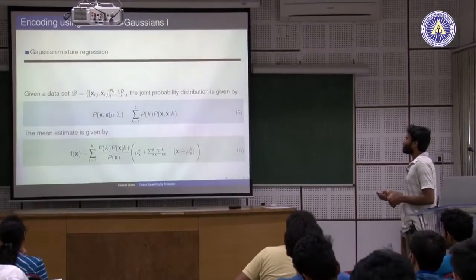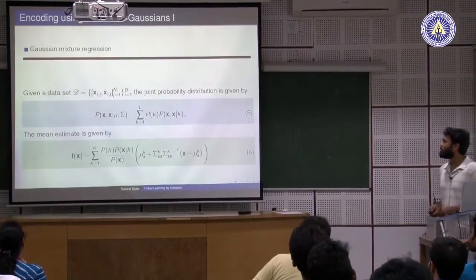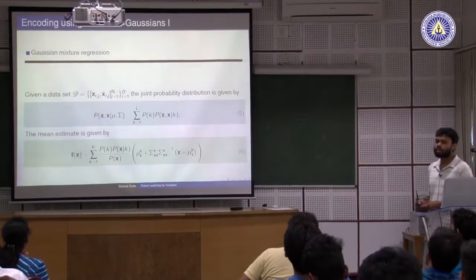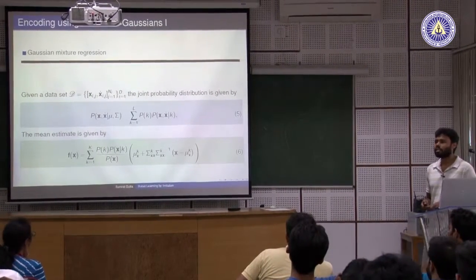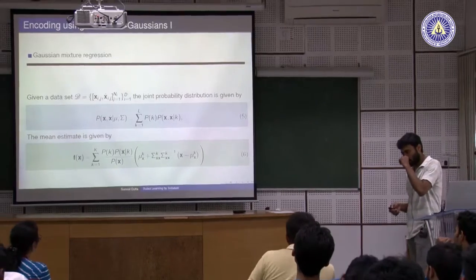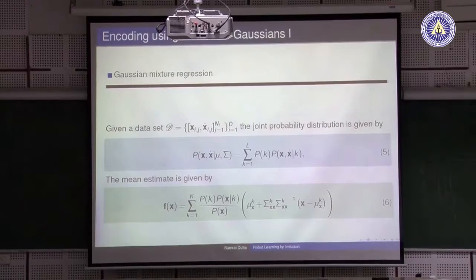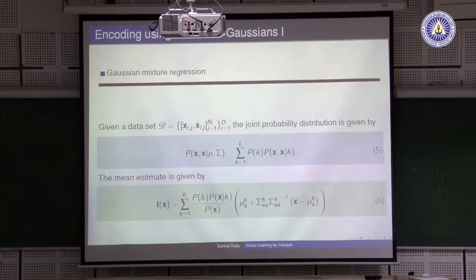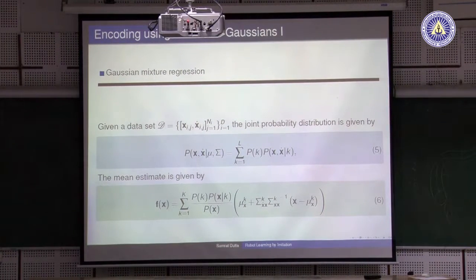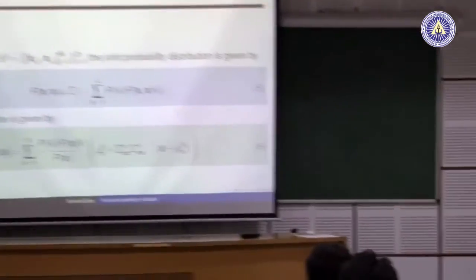Okay. Dynamic movement primitives have good applications, especially in playing table tennis. But the problem is that dynamic movement primitives learn in a single dimension. They do not incorporate the correlation among states. So for each dimension there will be one movement primitive. When you are learning DMPs for a robot, DMPs are dynamic movement primitives.